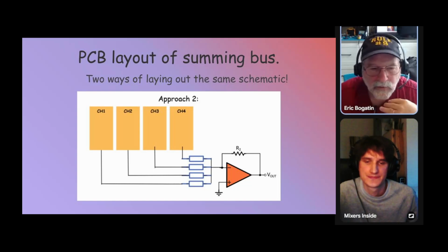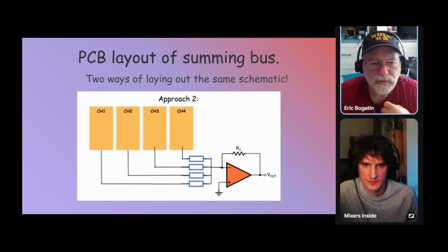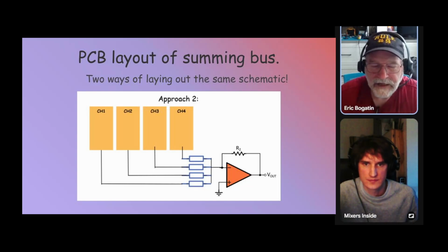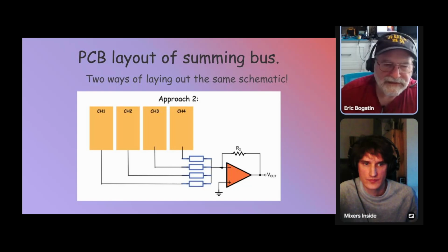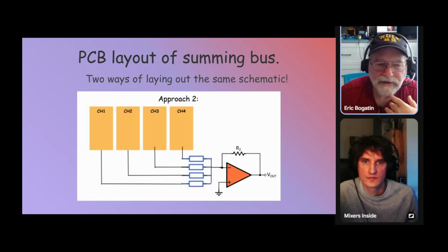Okay. In order to evaluate the impact, you want to think about the equivalent circuit model of the interconnect and how it behaves in your circuit. As long as the traces are microstrips, so there's controlled impedance, and you have a ground plane nearby, crosstalk from other sources is going to be low. There's some input capacitance of those traces that you can estimate roughly.